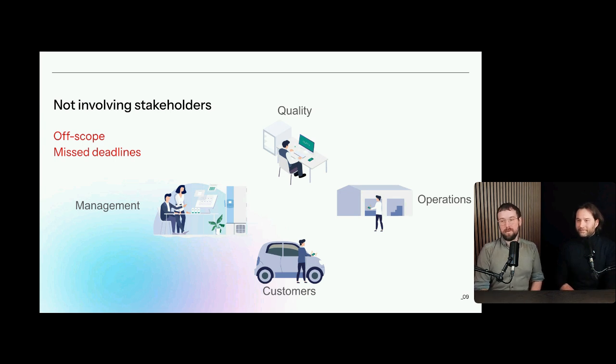I would totally agree with David. There's really not a specified number. Often what we do see, and it's one of the points later on here, is that if you plan for these sorts of deviations, it's often not that much of a cost to add a few extra data loggers, which means that if you lose some data loggers, then you've planned for it, so you can rely on the others. Often you would have to look at the distribution of temperature, find some data loggers in the vicinity of the data loggers that failed during a study, and see whether those can justify the lost data. So, just moving on.